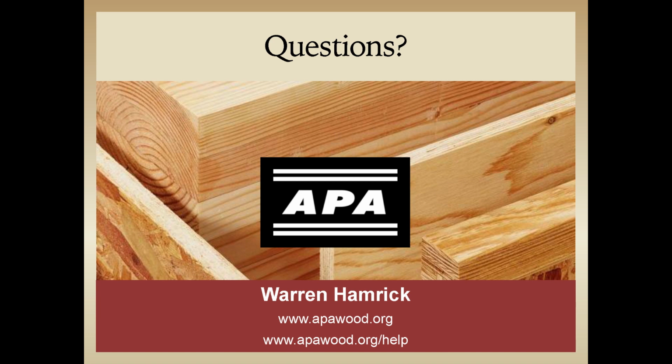Yeah, if you're using wood structural panels as your wall bracing, then what's going to affect the shear really breaks down to the fastening along the edges of the panels and the thickness of the plywood or OSB. That's made clear by the fact that if you're designing per the IRC wall bracing provisions and using wood structural panels, going from a 16-inch spacing to a 24-inch spacing does not change your wall bracing requirements. So that really highlights that what's critical is the fastener spacing along the panel perimeter and the thickness of the panel.